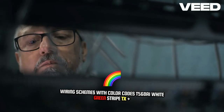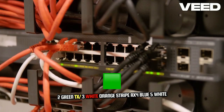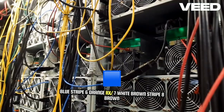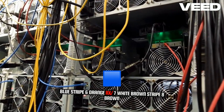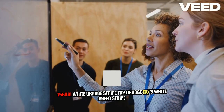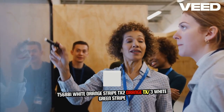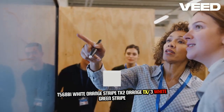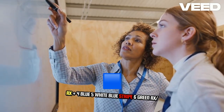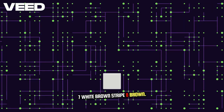T568A: 1 white green stripe, TX+; 2 green, TX-; 3 white orange stripe, RX+; 4 blue; 5 white blue stripe; 6 orange, RX-; 7 white brown stripe; 8 brown. T568B: 1 white orange stripe, TX+; 2 orange, TX-; 3 white green stripe, RX+; 4 blue; 5 white blue stripe; 6 green, RX-; 7 white brown stripe; 8 brown.